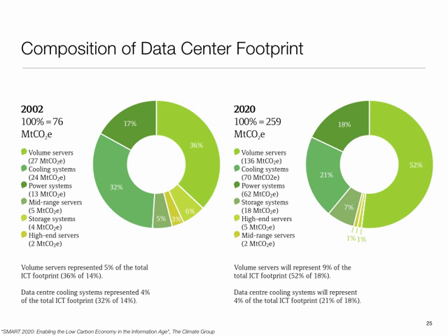What that translates into is every watt that I reduce on the computing side means I have one watt less to remove on the cooling side, and I will have to supply a watt less, which benefits my power system. So a unit reduction on the computing side has similar beneficial effects, and it just gets magnified all through. This is a place where one has to take this holistic picture.